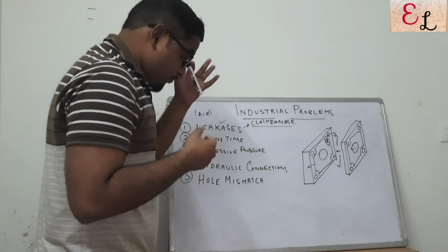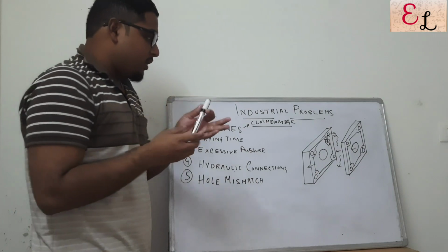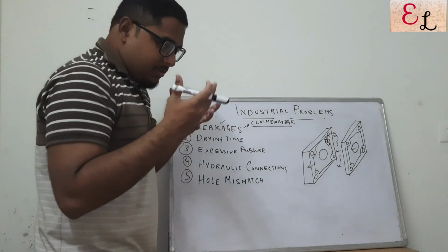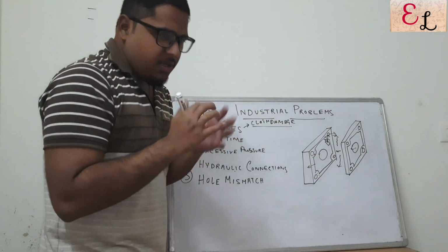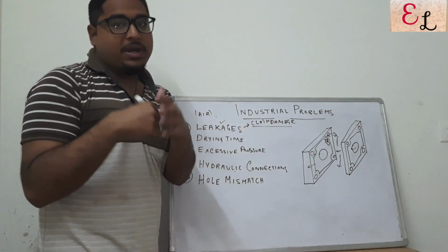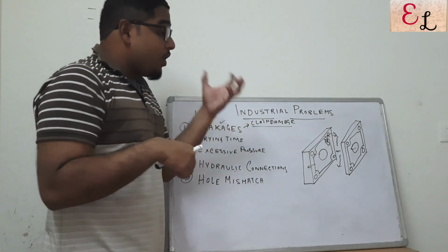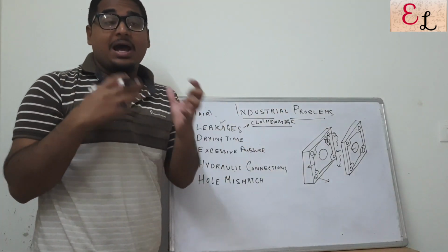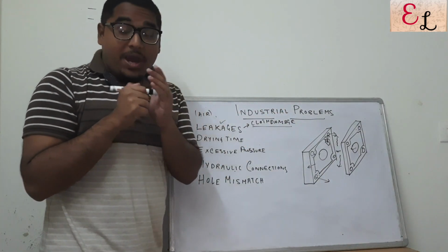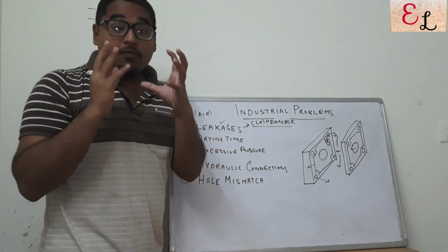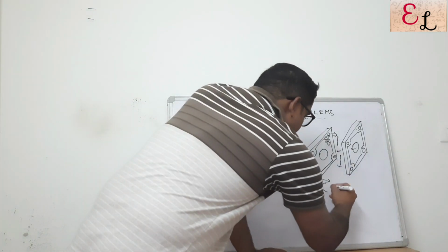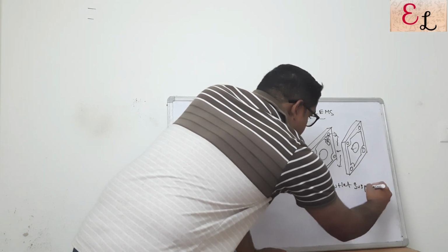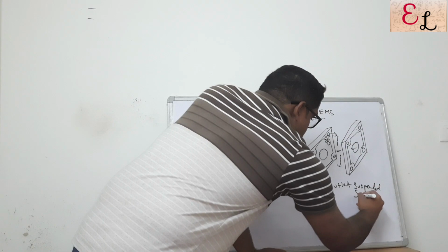same as compared to the inlet, which means that the outlet is coming out opaque, not a transparent liquid wherein the solids have already separated out. So if the outlet of the filter press is coming out very opaque or whitish in color, full of suspended solids, unseparated solids, what does it mean?